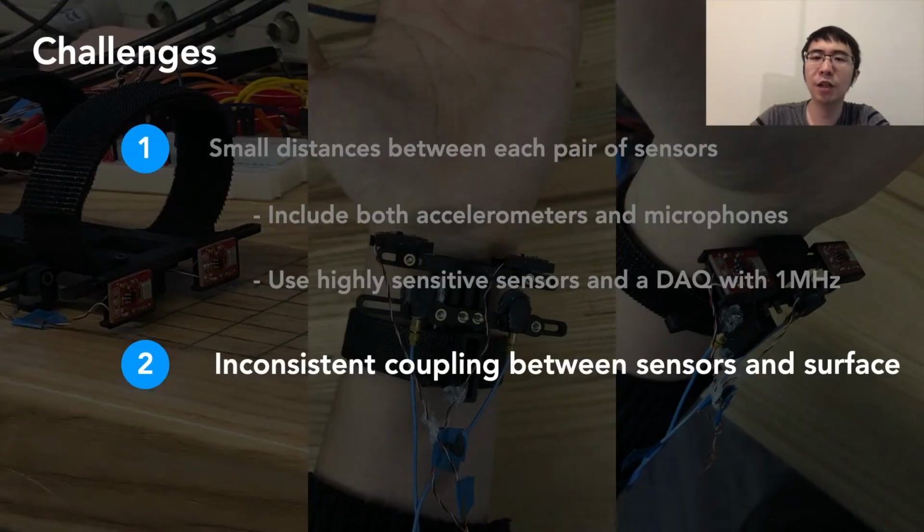Further, the second challenge of a wristband form factor is the inconsistent coupling between the sensors and the surface. Since the accelerometers are embedded on the bottom of the wristband, the coupling between the accelerometers and the surface highly depends on how users put their hands on the surface. And the accelerometer signals may also be affected by any hand movements right before the typing. Both introduce noise and instability in the received signals at the accelerometers. This inconsistency makes it difficult to reliably locate the taps by simply using mathematical triangulation.